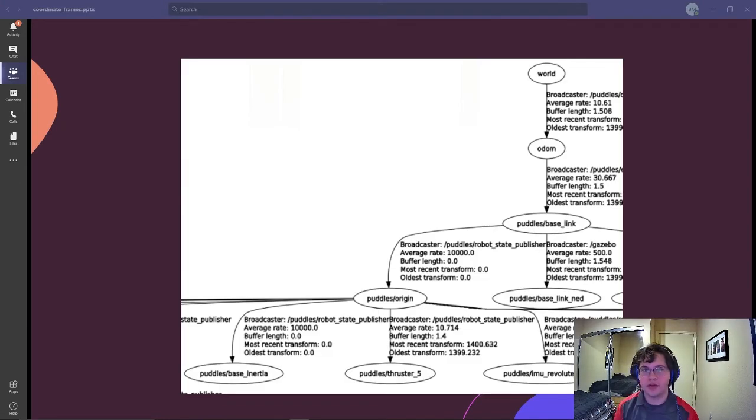So to represent all of these coordinate frames in code, we have a tool called TF. TF is the tool in ROS that will actually take all of these coordinate frames, recognize the transforms between them, and update it with time, and even keep track of where the transforms between things were at different points in time. So every coordinate frame has a transform, or a defined mathematical operation, to define what the second frame is in the first frame.